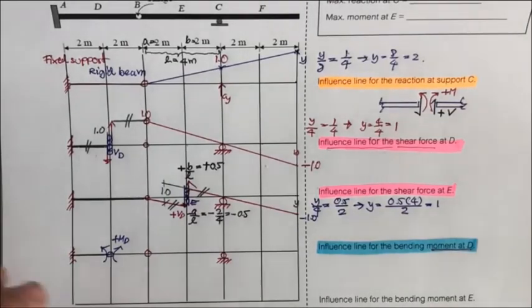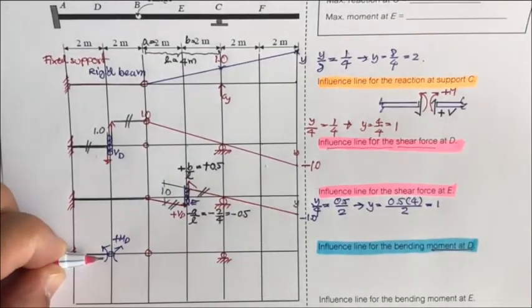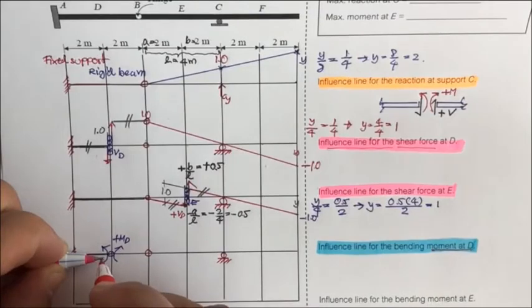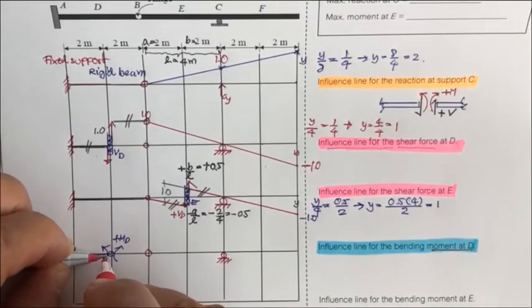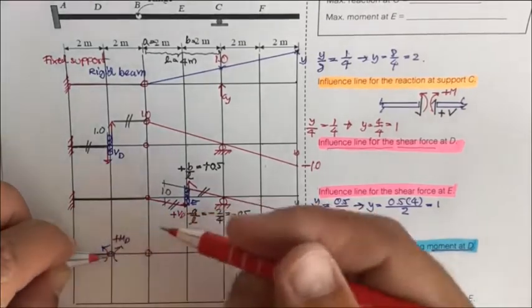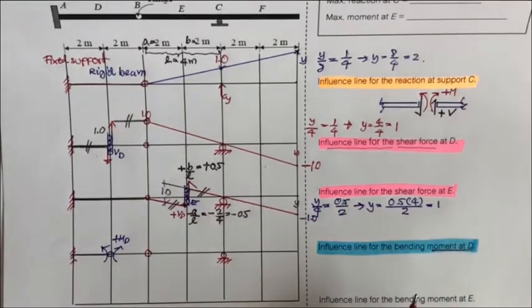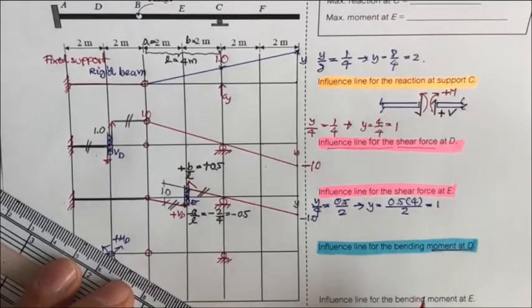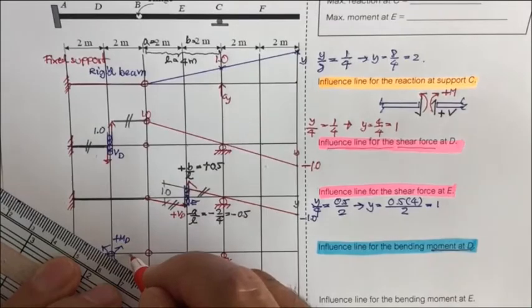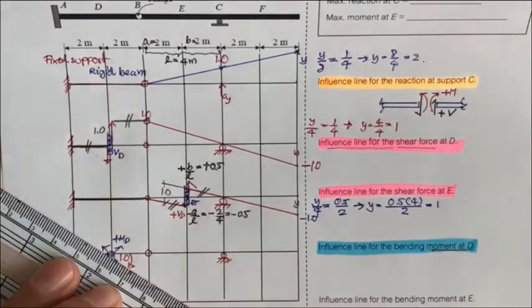And then what happens is, this is a stiff beam, and if you try to rotate it, the fixed support won't allow the rotation, see? So this one will not move at all. So the portion here must move, and it must rotate by 1.0 radian.